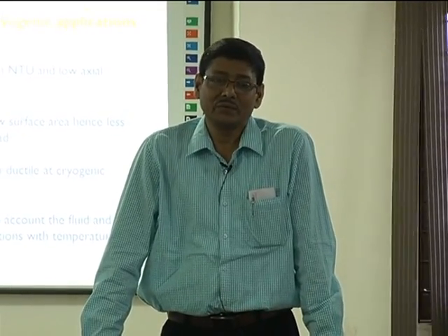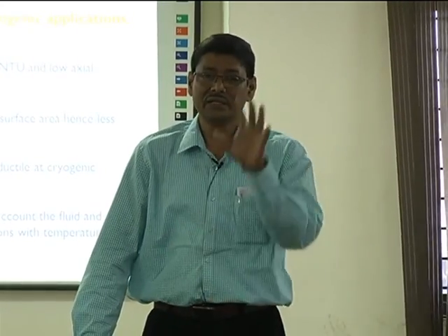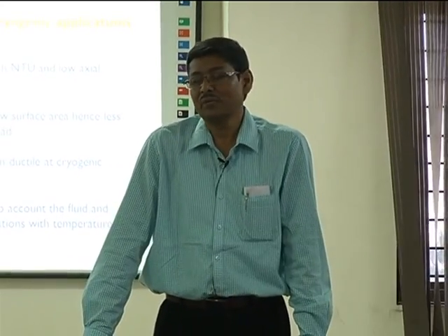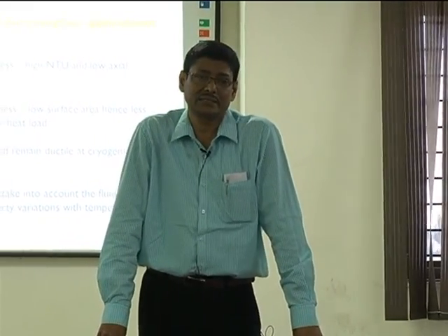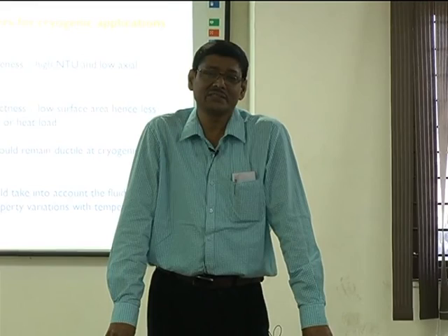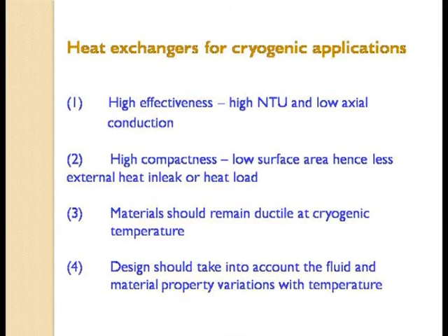That means to have high effectiveness heat exchangers, 98% or 99%, you must have almost negligible axial conduction in the axial direction, and there comes the greatness of the heat exchangers. Okay. So maybe as we proceed, we will further learn how this axial conduction is minimized and how it is taken care of in the case of cryogenic heat exchangers.